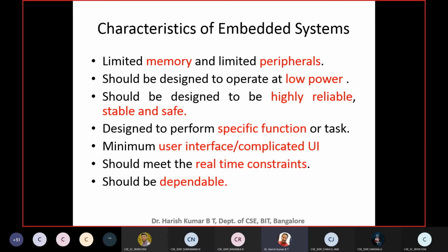All the critical embedded systems which I mentioned, like heart pacemaker, insulin pump system, and ABS, will be running a hard real-time system, where there are rigid timing constraints. If there is a task which should start at some time and complete its execution at the designated time, it should start at that time and complete its execution within that time, and no delays are entertained. All embedded systems should meet the real-time constraint. Some should meet the hard real-time constraints, and some the soft real-time constraints. And I gave you the example of TV set-top boxes for the soft real-time constraints.